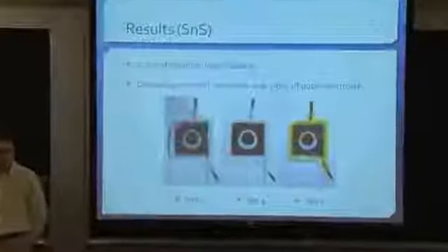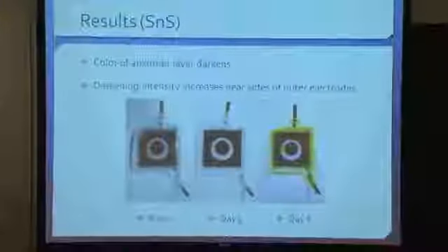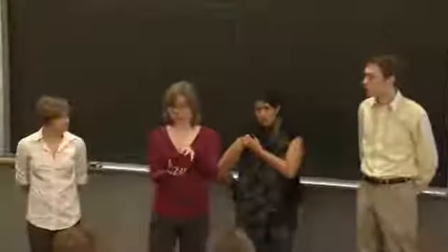And the devices, both devices that we worked with, were kind of hard. They aren't meant to be encapsulated. So I think part of the problem is just the geometry of the device and the presses that we use. We probably just didn't get a very good seal around the outside. So in this case in particular, I think it's more likely that it's just not a very good seal, so we're getting some leakage, rather than the tin sulfide reacting with the EVA.